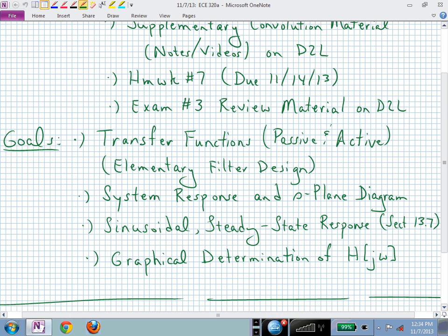If I had a break frequency at 5 radians per second, and I said a decade beyond that break frequency, what frequency would we be talking about? A factor of 10 beyond 5. 5 times 10 is 50. So a decade beyond the break frequency at 5, you're at 50 radians per second. If I said a decade before 5, now you're dividing by 10. Now you're at 0.5, half a radian per second.